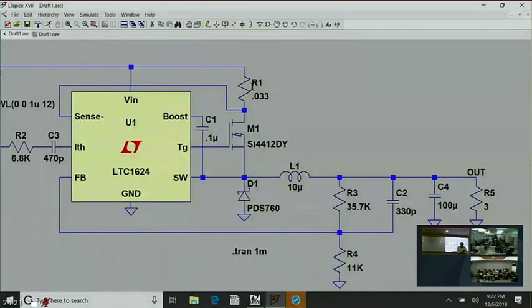It increases the efficiency of your controller, because buck controllers are rated by how high of a voltage bucking ratio they can buck in one step. If you can buck more voltage ratio in one step, it's a better buck controller. And if you buck a high voltage ratio, that switch is off almost all of the time, so you're almost never putting current through the current sense resistor. It's a great technique. All right.